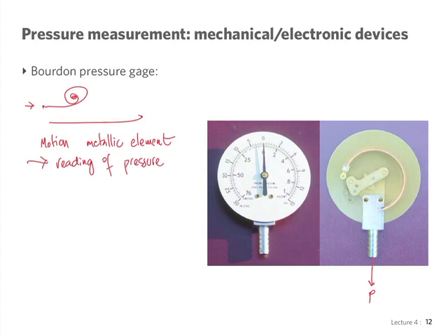What do you think would be the pressure when this reads 0? Atmospheric, very good. Equal to atmospheric. One thing you can notice here is that we have numbers on two sides of 0, because just as we can blow into this little tube, we can also apply a negative pressure. So this reads both negative and positive pressures around the atmospheric value.